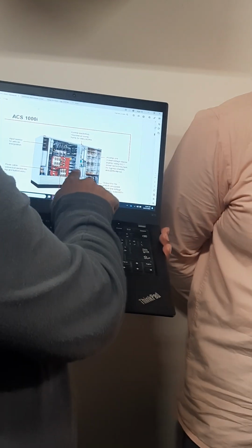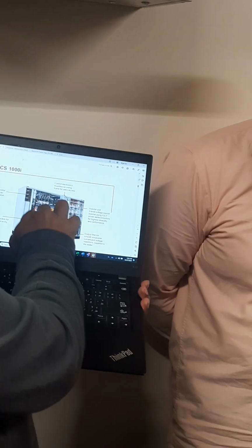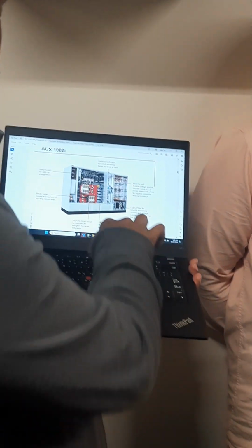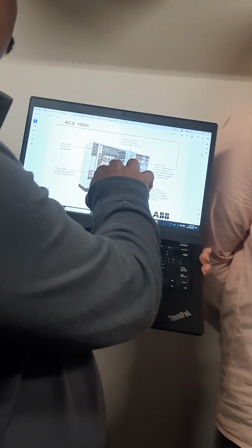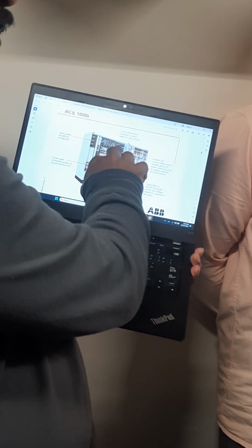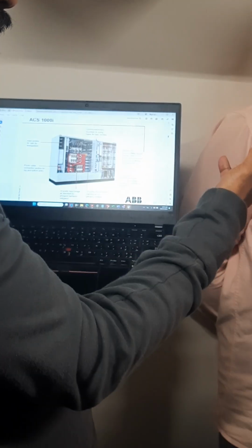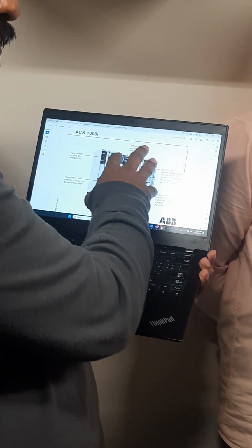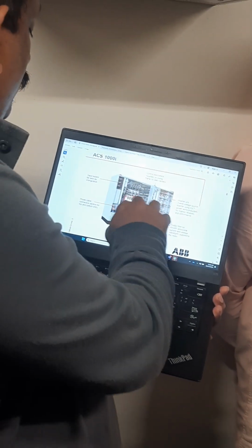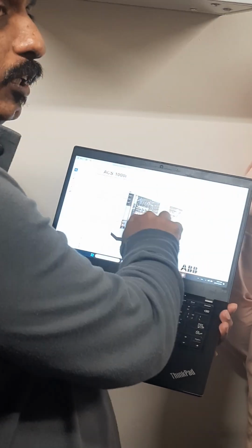After this you have the transformer, and here we have the thyristor diodes, 24 thyristor diodes. The input is here. They convert AC to DC. Then we have the IGCT protection here. Any short circuit on the DC side, it will open and protect. It is 100 times faster than fuse units. So we mainly have these components here, and some resistors and busbars.